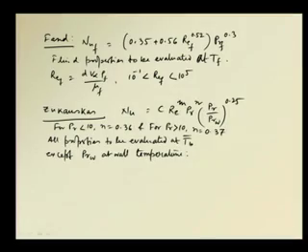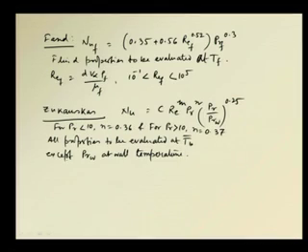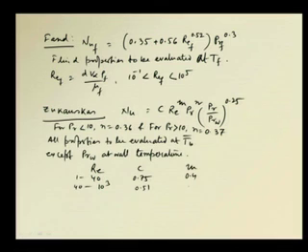T_B bar is the average bulk temperature that we have already discussed, and the values of C and m can be found based on the Reynolds number. So, if we have Reynolds number here, C here and m here, from the table we can find that for Reynolds number 1 to 40, C is 0.75 and m is 0.4, and from 40 to 10 to the power 3 it becomes 0.51, and here it is 0.5, then 10 to the power 4 to 2 into 10 to the power 5,